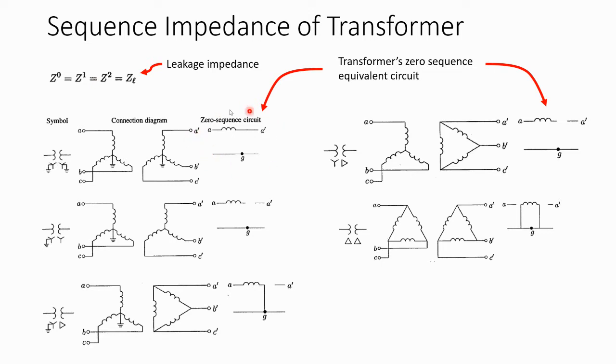Just now we mentioned that this is similar to the positive and negative sequence transformer, but I recall that in the three-phase balanced fault analysis video, we never considered the connections of the windings when determining the equivalent circuit of the positive and negative sequence transformer. And rightly so, because the positive and negative sequence circuits of the transformer are not affected by the connections of the transformer.